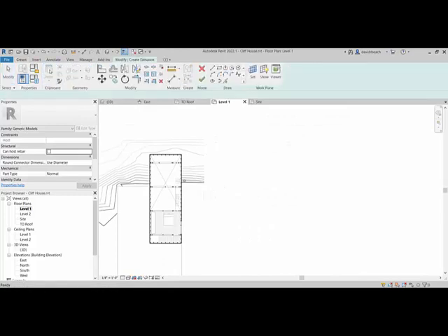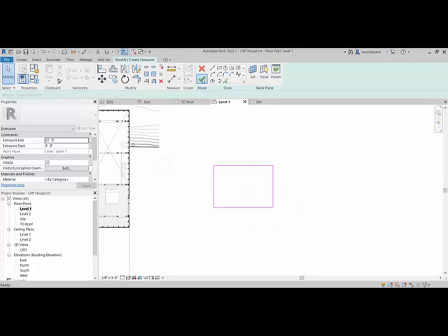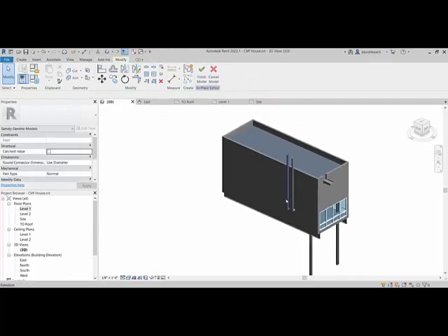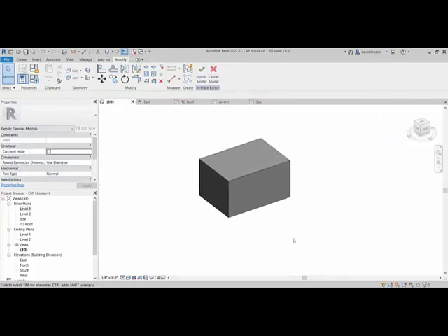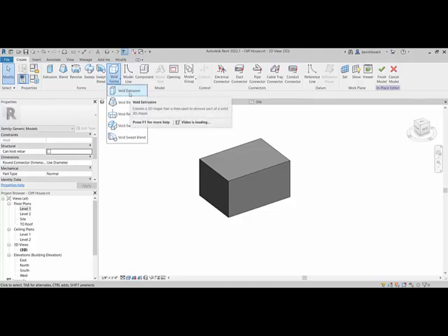So if I do an extrusion and a box, okay, I've got that. If I come in and do create void form, I've got my same list of objects. Okay? I would say 9 times out of 10, maybe 99 times out of 100, I'm using a simple void extrusion on this.